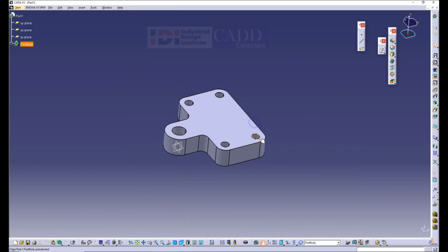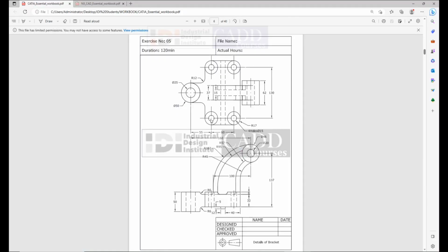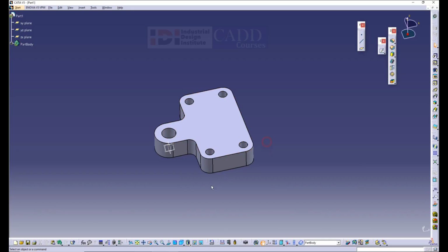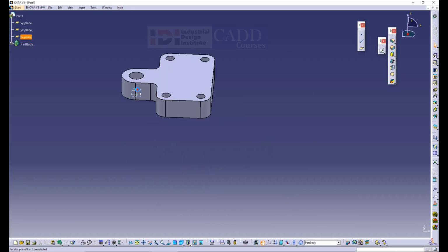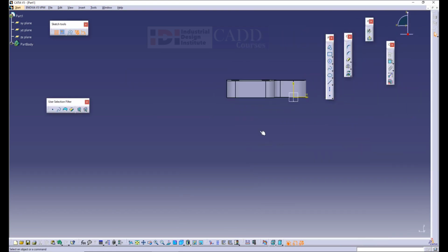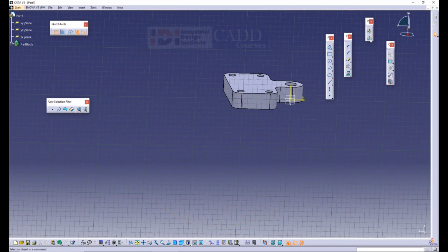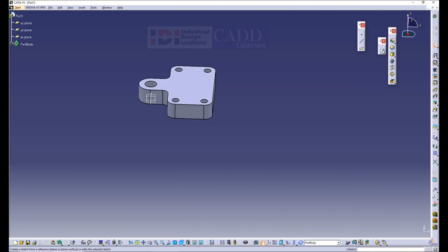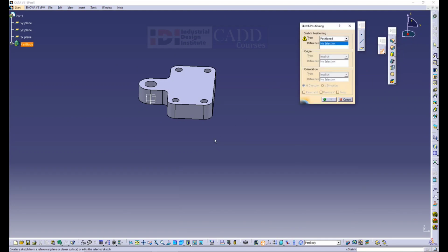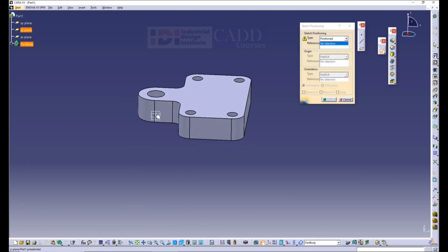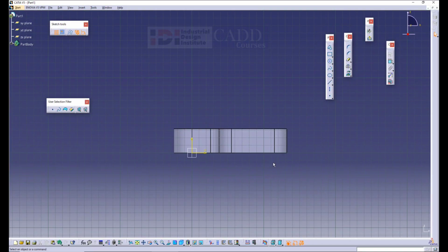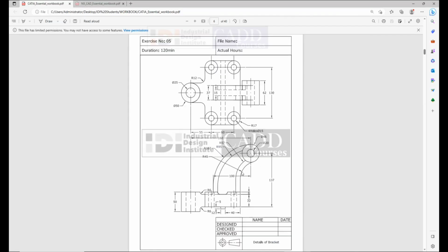After the 32 mm thickness, I'll make a side view, the side part, which is like a lever. I'll create the lever with respect to the center plane. You can see the model is getting tilted. I need it properly aligned, so you can see this horizontal line. I'll reverse it and make it straight. So now it is proper.